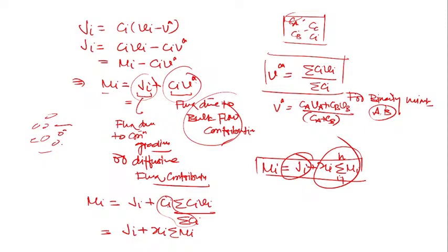and suppose in this case you also want to swim, you also have the ability to swim, then your swimming ability plus the speed of the water is also moving. So both will contribute to the total, yes, no? Then the total flux will be the sum of your own contribution and the contribution of the bulk flow. Is this clear? That's what I told you. This is the flux due to concentration gradient, or diffusive flux contribution, and that is the bulk flow contribution. So both will sum to equal the total contribution, total flux.